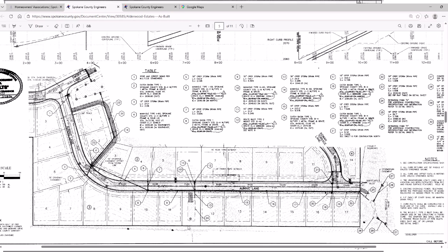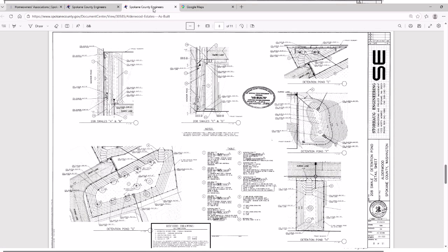If you look here at item 24, between these two lots, we can see that item 24 was for Detention Pond H. These detailed sheets are helpful for stormwater management because they provide specific information important to the operation and maintenance of each facility, including but not limited to its size and water storage capacity, its design features such as the side slopes, inlets and outlets, safety features such as fences, and maintenance access roads and any access easements.